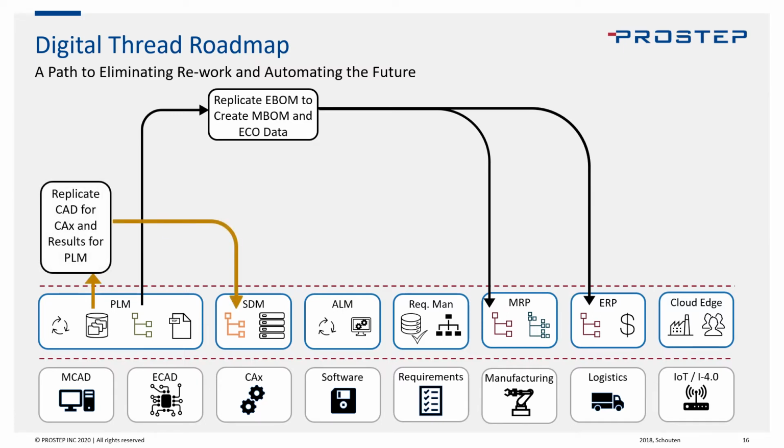The second is replication of CAD data and then bringing back results to PLM through your analysis data management. That could be SDM, simulation data management, or SPLM. This is taking data from your product lifecycle management system and the actual binary CAD data, bringing that into your analysis data management system, performing that analysis, and then bringing the results back so the designer can update it. And this is something we're seeing a lot of traction on within different aerospace and some automotive communities.